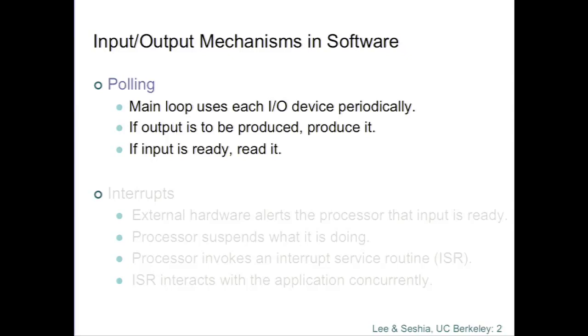So one of the ways that you can get deterministic behavior and still do I/O is polling. And in fact, this is typically what happens in an avionics system, the flight control system in a commercial aircraft. Suppose you have a temperature sensor that is telling you the temperature of the engine at some point in the engine. The software will periodically go and query that sensor for a value. Now, it might be a lot more efficient to just have that temperature sensor tell you when there's a significant change in temperature, for example. But that would not be a polling strategy. That would, in fact, require concurrency to do that.